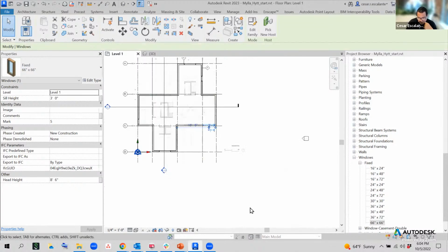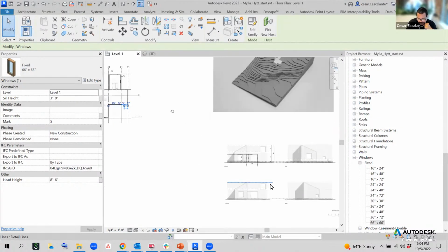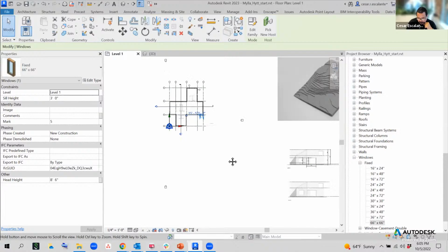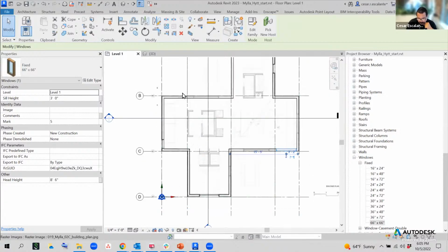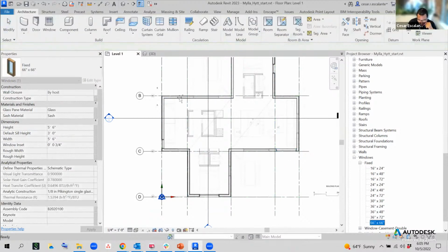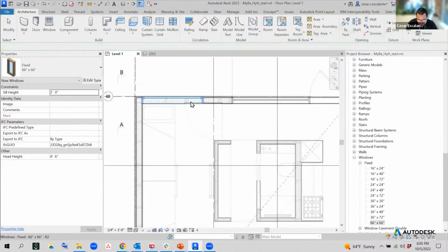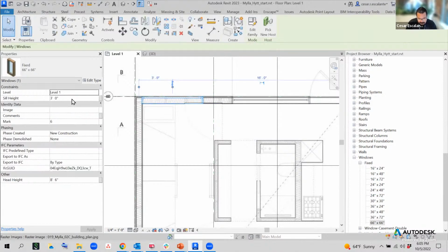And so the north elevation also displays a clerestory window that is in this location here. I'm going to put another 66 by 66 right here. Also, remember to change the sill height. The sill height is 9'4".